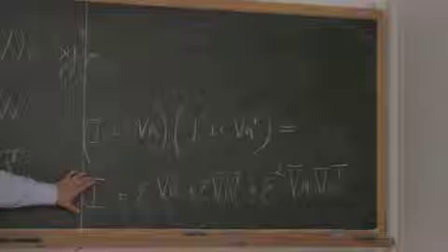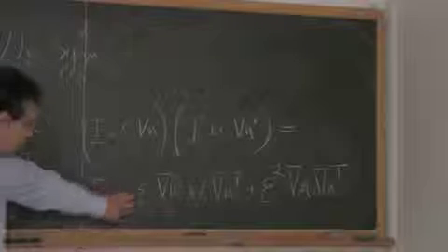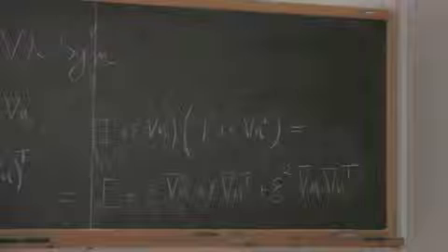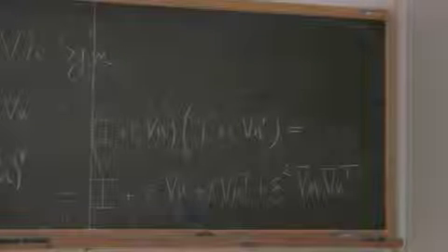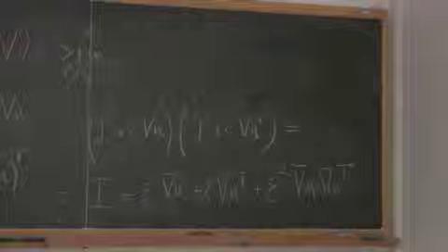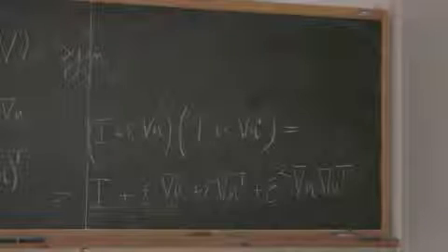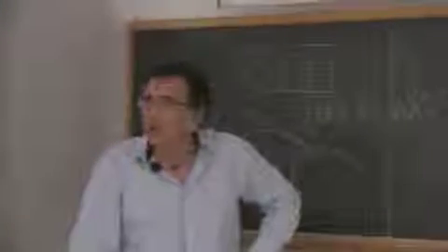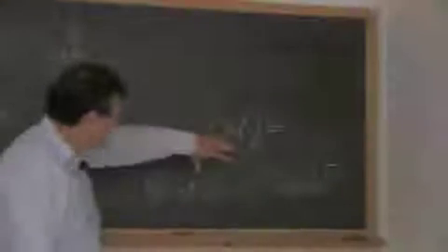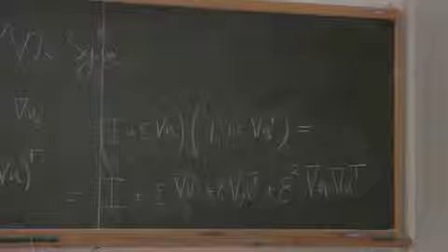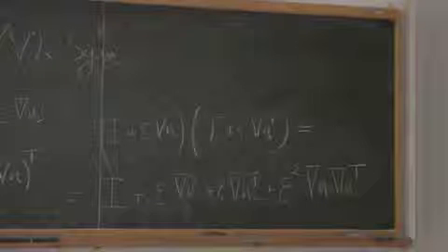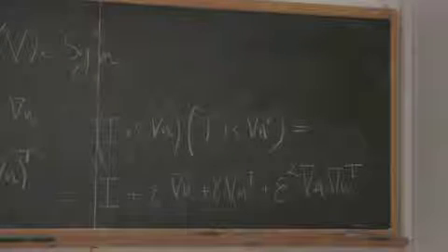So the Green deformation tensor is the identity plus epsilon times the double of the symmetric part of grad U plus epsilon square grad U transposed grad U. Now, if I can neglect so-called geometrical non-linearities, so if I can neglect epsilon squared there, the Green deformation measure reduces to the symmetric part of grad U, because 2 times 1/2 is the same stuff.